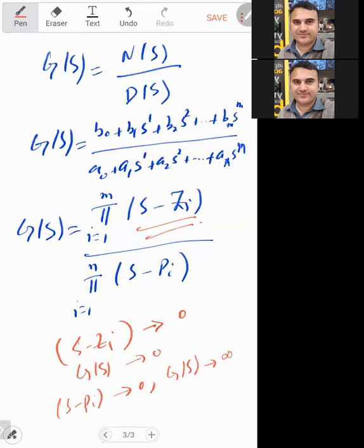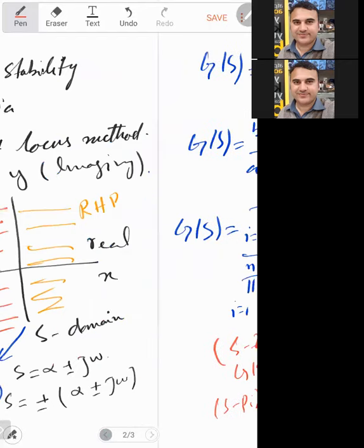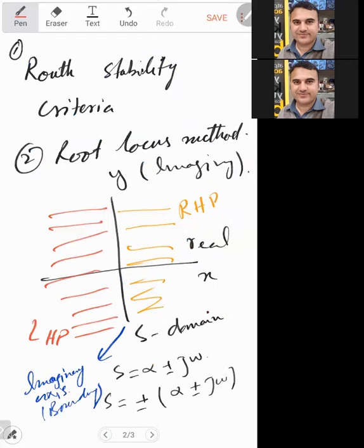So mostly we are interested in the pole information, because the pole at the origin gives the forced response or the steady state response of the final output function. We discussed this in the previous section. But a pole at any other location will give us the transient response, and we want to make the transient response equal to 0 so that we achieve the stability or the steady state response of the system.